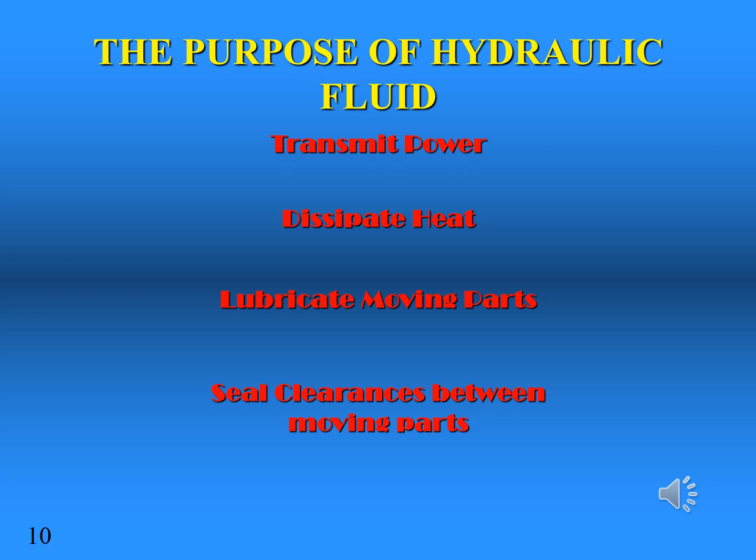The major function of hydraulic fluid is to provide energy transmission through the system, which enables work and motion to be accomplished. Hydraulic fluids are also responsible for lubrication, heat transfer, and contamination control. So it's a lube and a power transfer device. This dual role makes it unique.